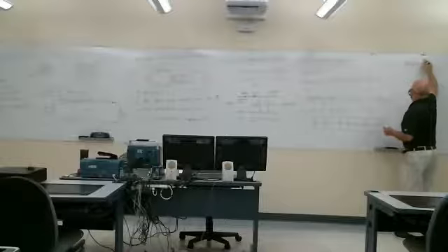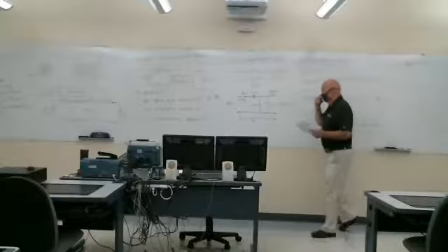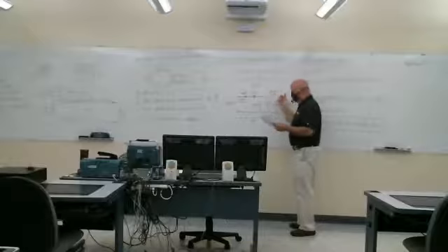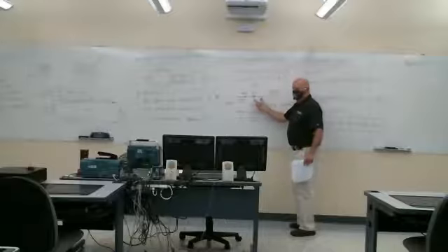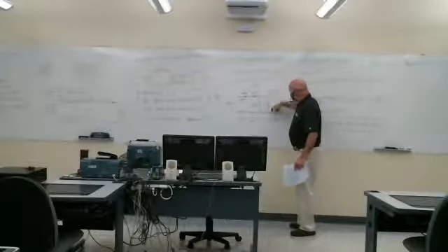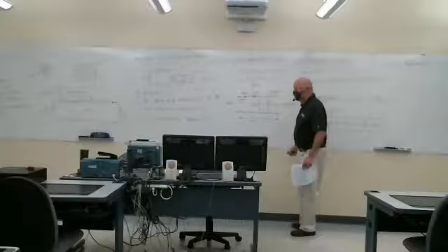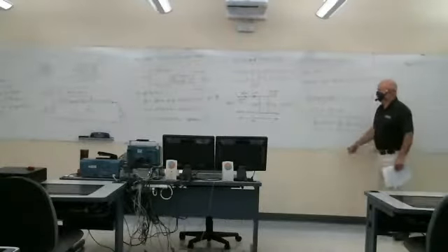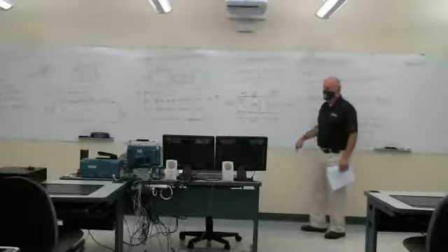Similarly, applying Kirchhoff's current law at this node, we've got I going out, I(z plus delta z) going out, and I(z) going in. The current flowing through the capacitor would be the capacitance times dV/dt. And the current flowing through the conductor is not V over R, it's V times the conductance. The current flowing through the conductor would be this voltage times that conductance.